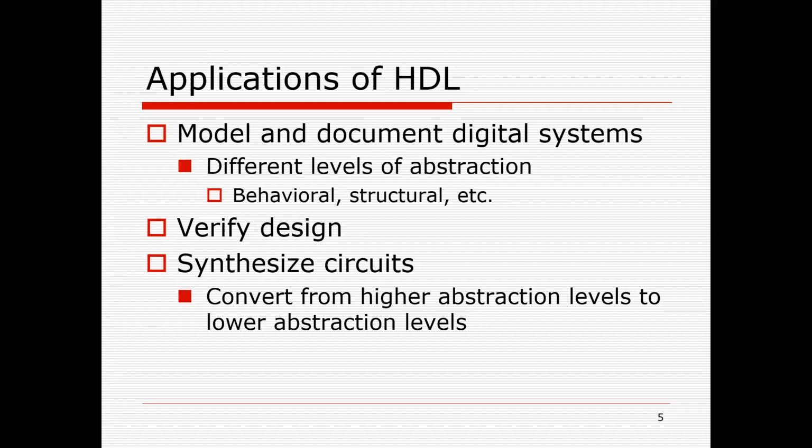Now it depends. Would you like to check for all the combinations? Because if you have a 16-bit adder, you have two operands, and each operand can have 2 to the power 16 variants. So you need to combine each and every variant of the two operands to test it 100%, which is typically not done. You pick up only select cases which are critical or significant, and if they work, you say my design is working. And most probably, 99.99%, the design will be working.